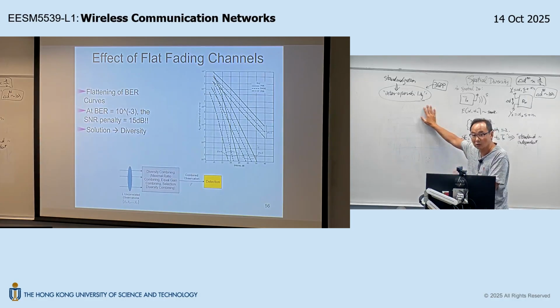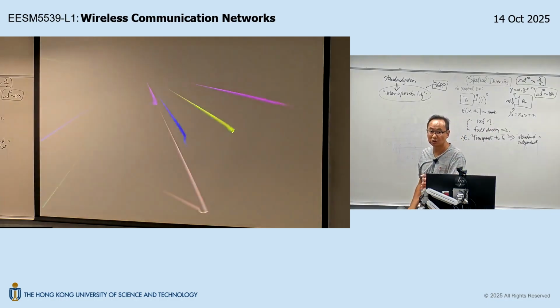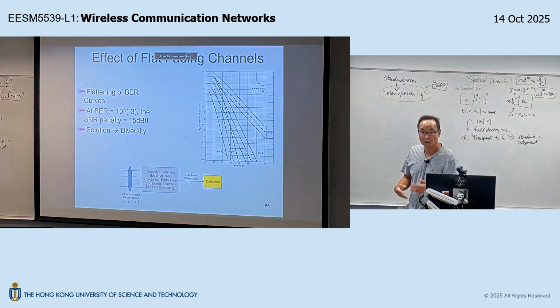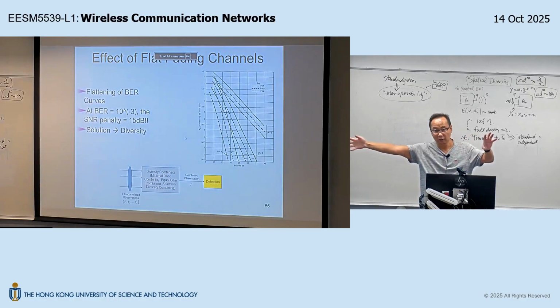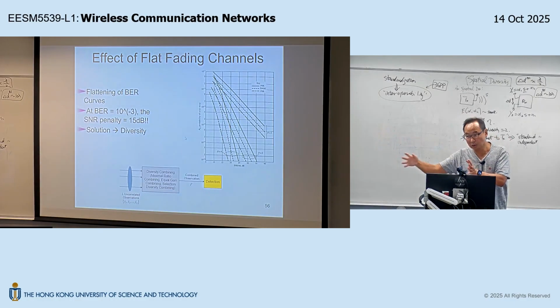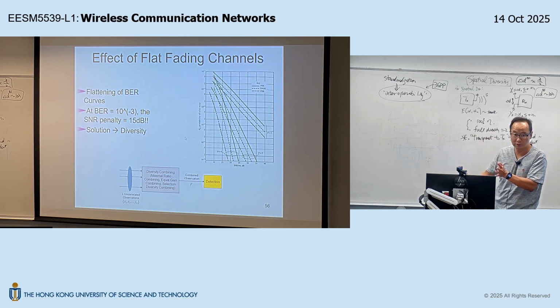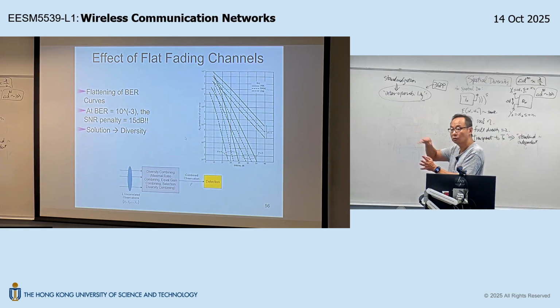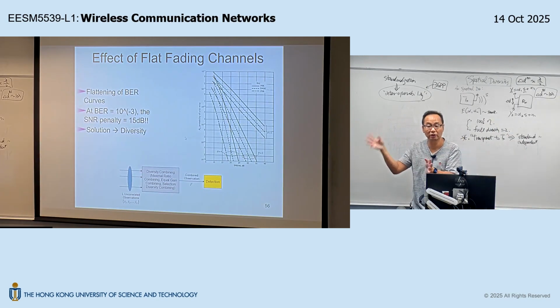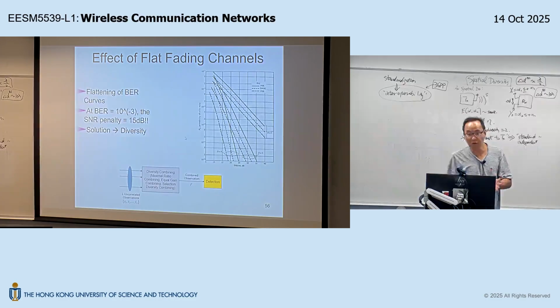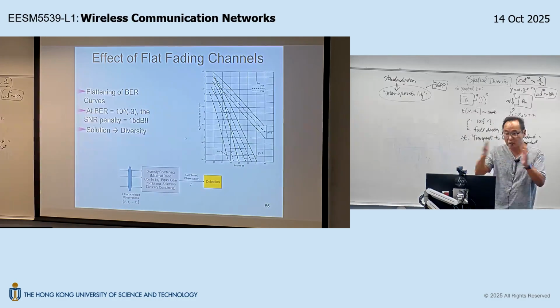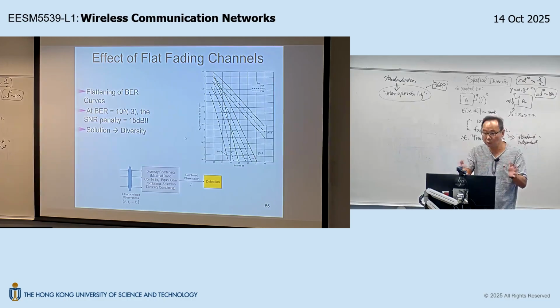But on the other hand, for the receiver, how you do the demodulation, how you do the channel estimation, how you take the observations and process them to get the output, these kinds of details are outside the scope of standards. So standards usually will not specify too much about how you do receiver processing. Okay? They just need to make sure that the radio interface, the frame for the data, the frame for the signaling, conform to some requirement. Okay?